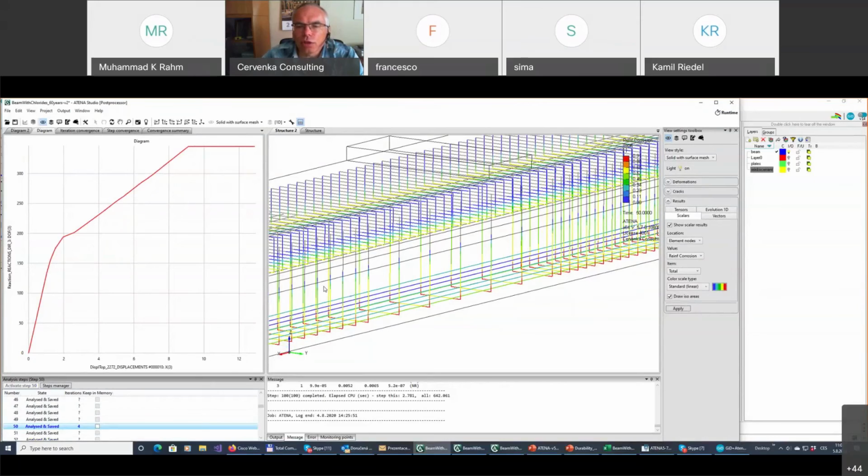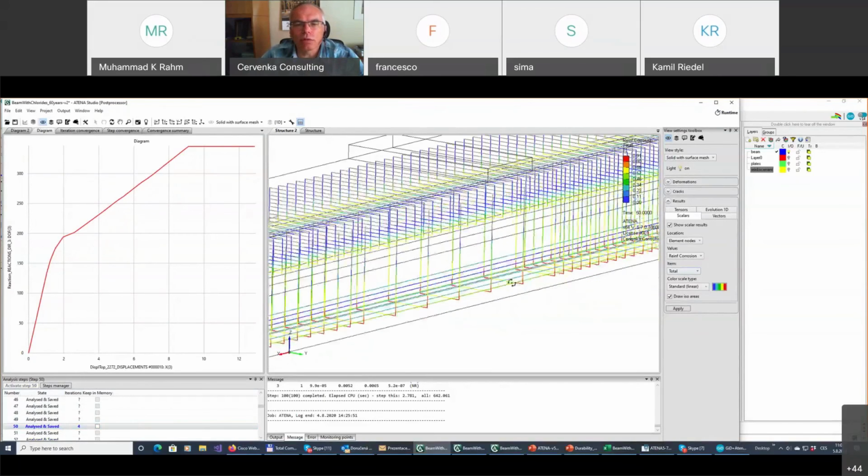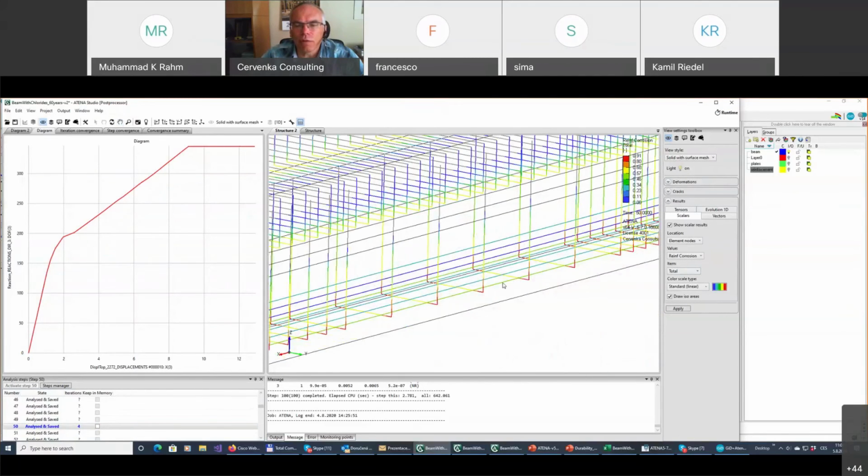Well, in this particular situation, the effect of the crack width is not so pronounced, because you really need to have very wide cracks. If the cracks are, let's say, below 0.1 millimeters, the effect on the chloride propagation is not very big. This is also why the codes require you to have crack widths smaller than 0.3. But once you have larger cracks, then there is a significant effect on the chloride propagation.